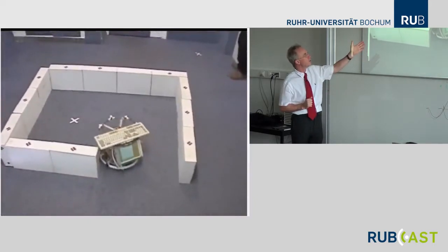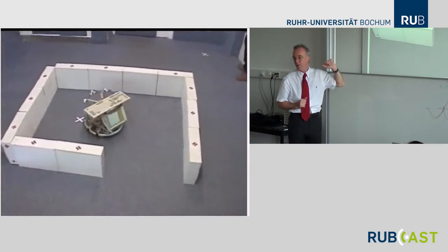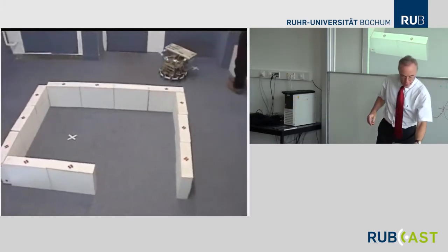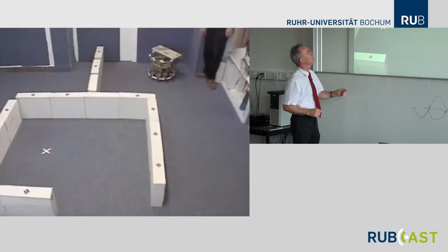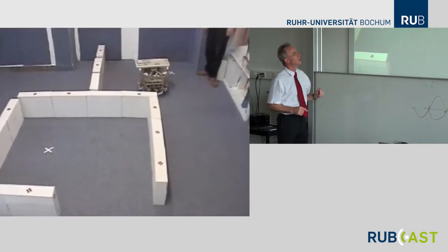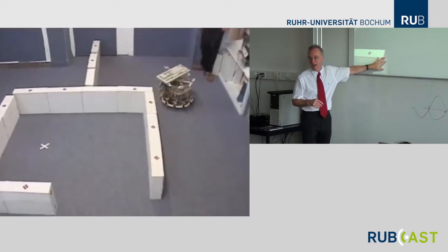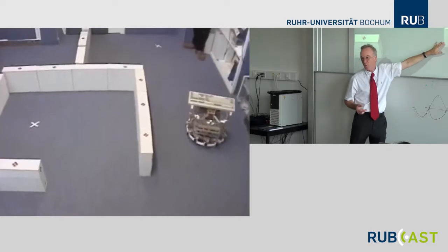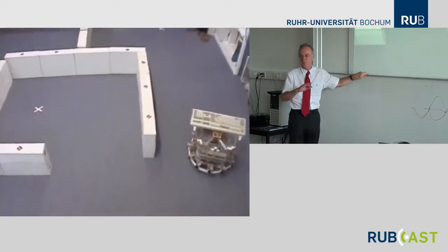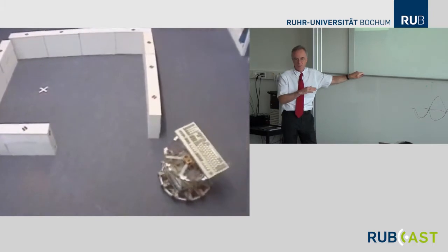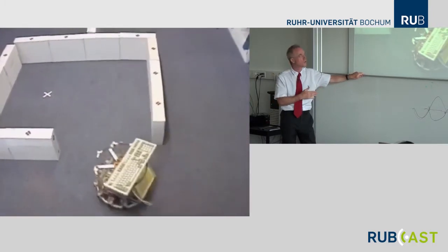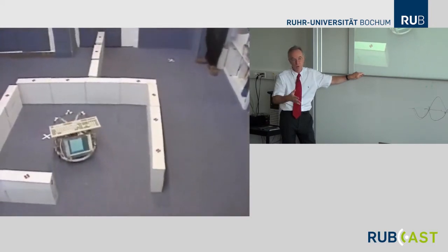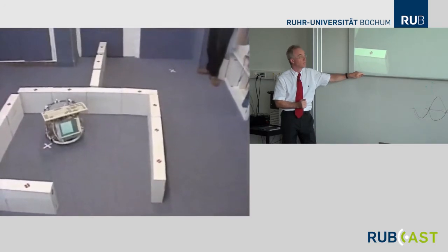So this shows the robot actually finds the target, even though it has only a local plan. It does this with attractor dynamics. Here's another example. Now we block the road and it finds the other direction, but it doesn't know that. It's just following walls essentially, always trying to go this way, being pushed away from these walls. What I'm trying to make the point with is that, in some sense, global behavior can emerge from local behavior if the environment is right. If the environment is walls with a few openings, the system will tend to find targets quite well.